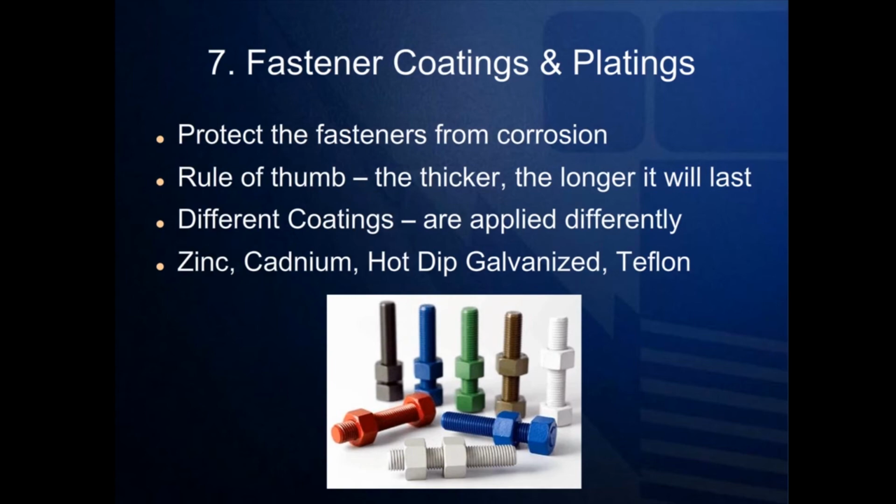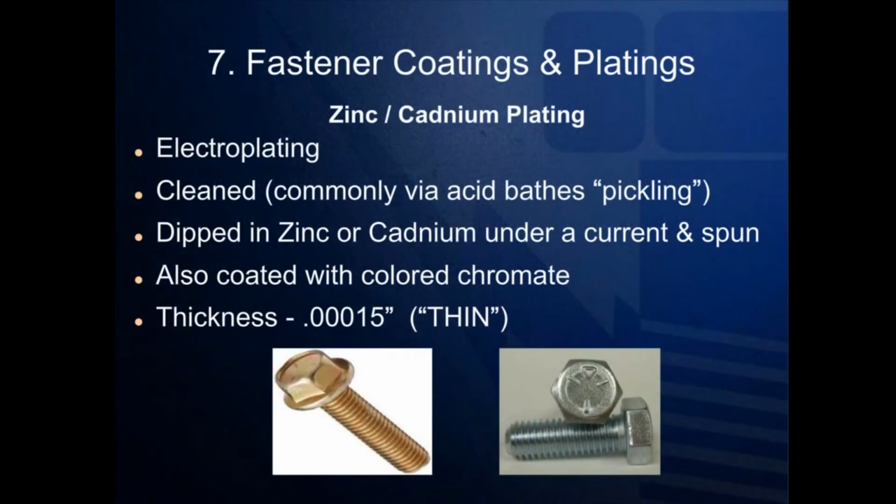We will now go into detail as far as the processes of zinc plating, hot-dip galvanizing, mechanical galvanizing, and Teflon coating. Zinc is the most popular of all commercial platings because it is relatively inexpensive and offers good corrosion resistance in environments not subject to excessive moisture. Cadmium plating results in a smoother surface and greater resistance to white oxidation spots than zinc plating. However, since cadmium is more toxic than zinc, which makes the plating process more difficult and costly, it is less common.